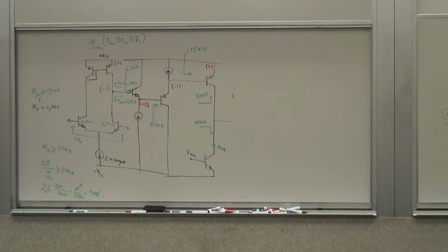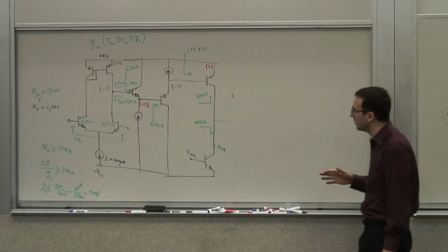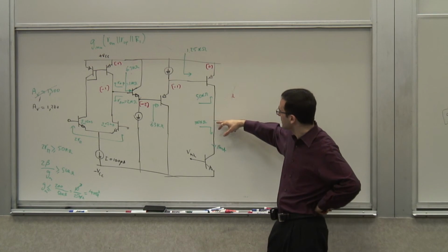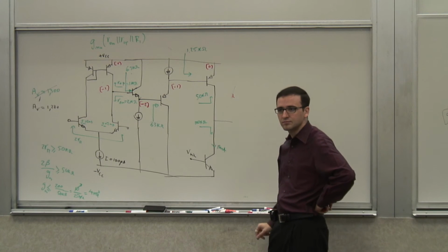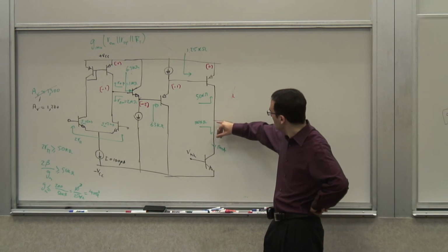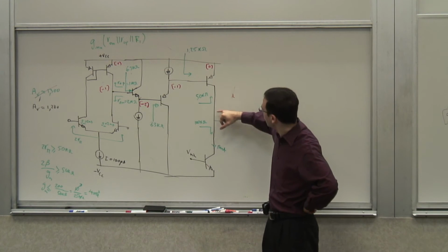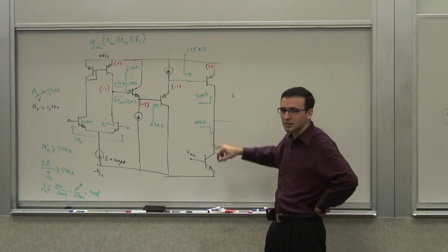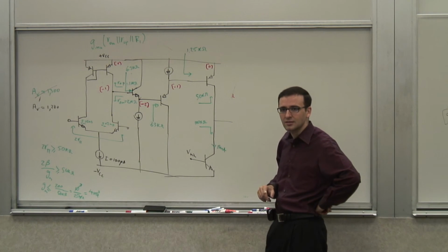Now, but this time, I remember one thing, that in principle, this node, how high can it go or how low can it go, in terms of the voltage swing? Large signal. So, what is the highest voltage this guy can take? VCC minus VBE. Why VBE? VC sat, right? The saturation voltage.